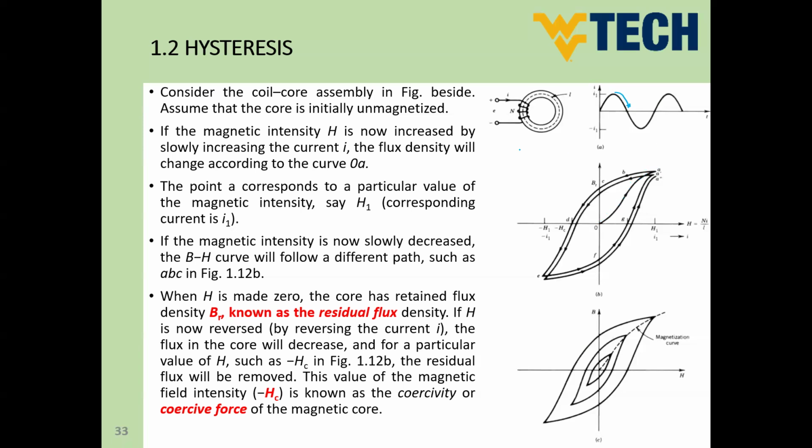Why, guys? What happened? What's the meaning of creating magnetic flux? The material includes many particles inside. When you apply flux, the flux will start moving these particles. In the beginning, these particles were not uniformly distributed in the material. Once you disconnect the supply, these particles will not return back to their random positions again. So even if you disconnect the electricity or the flux from the magnetic material, you still have some residual flux inside.